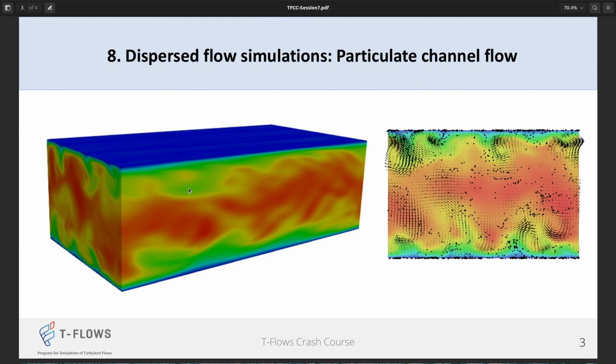But usually for benchmarking, just for your knowledge, we impose particles once we have the fully developed flow state. Otherwise, you don't really know what to expect from particles, because the flow is still adjusting the boundary layer, and you have, let's say, a profile of RMS values, and you need to have a clearer picture before you impose your particles. Otherwise they go everywhere.